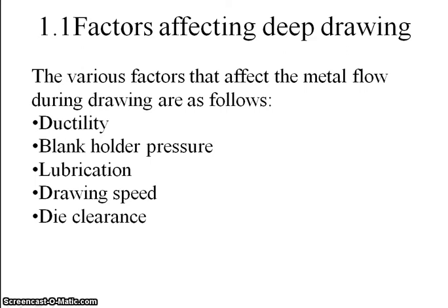Shallow draws in light stampings can be produced with little or no lubrication. But when forces become larger and wrinkling and tearing become a problem, lubricant is necessary.